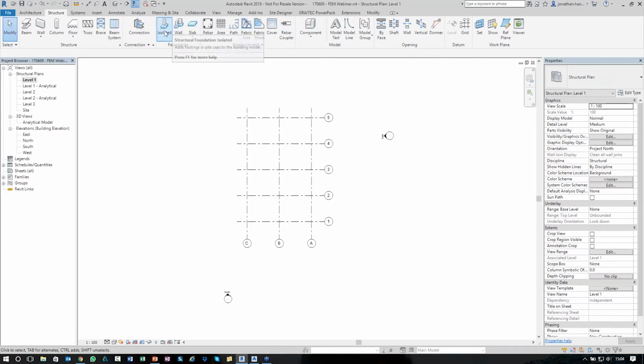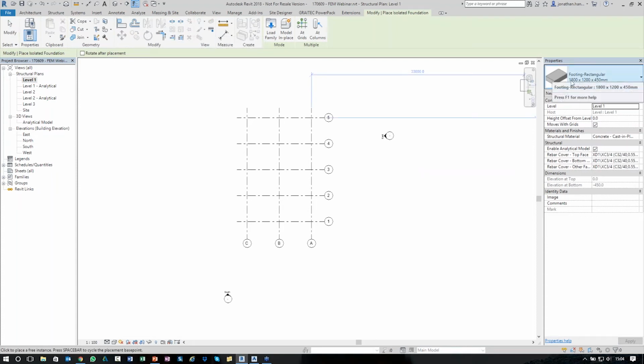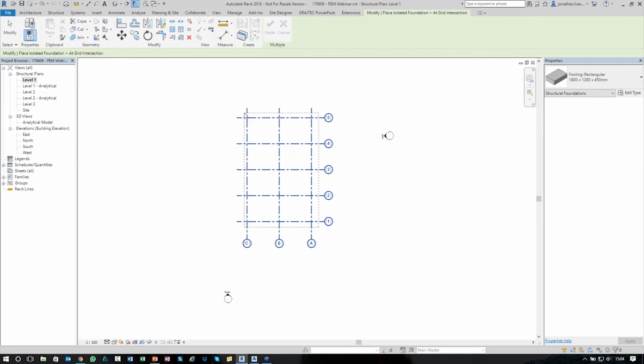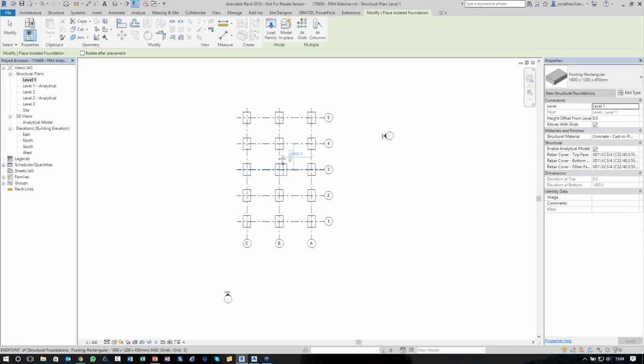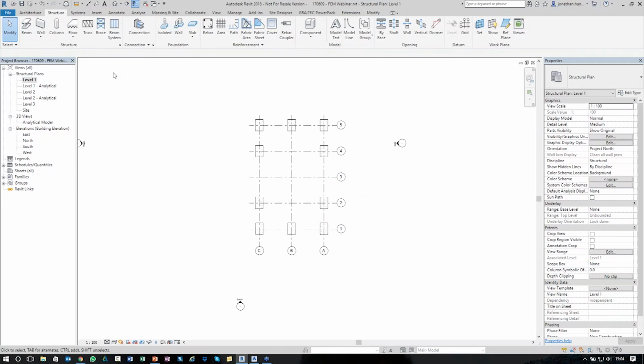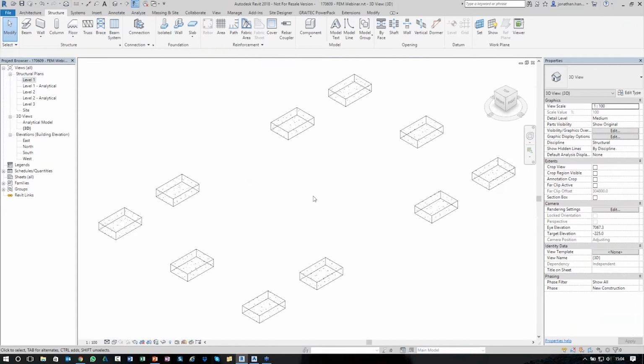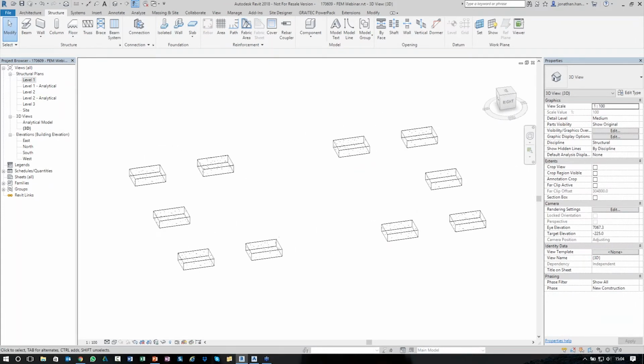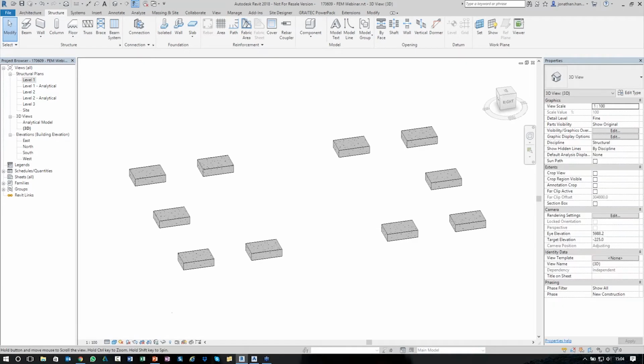Some of you who already know Revit know this is pretty simple stuff. Once I've got a grid structure in, I'm going to go straight to my elevation, and again I like to tidy up everything so that it looks correct. I'm going to add a new level into my system, and I'm going to put that, let's say, 1800 up there. So I've got the basis of what I want to create: some grids in and a level structure.